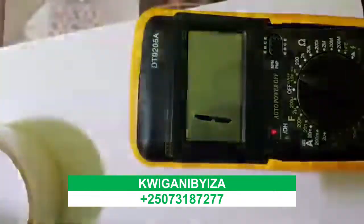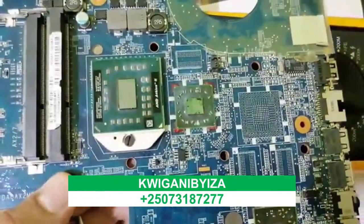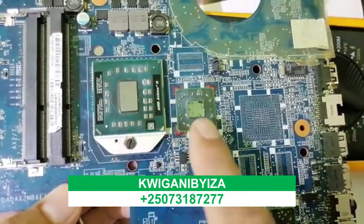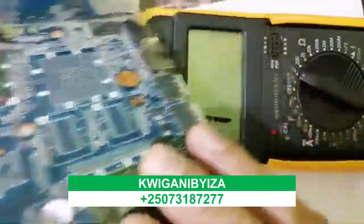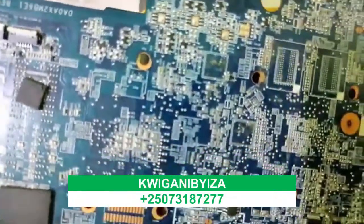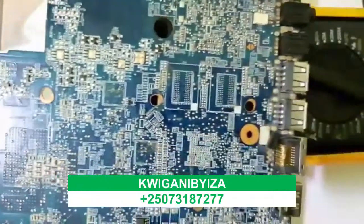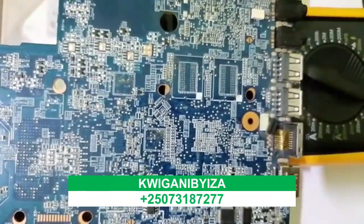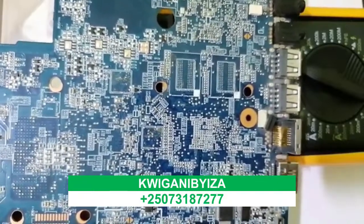So please, guys, remember, always for chipsets, okay? Always for chipsets like the CPU, the graphic card or North Bridge, and the ICH, the ceramic capacitors that you are going to find at the back of the chipsets, you will always find a very low resistance.